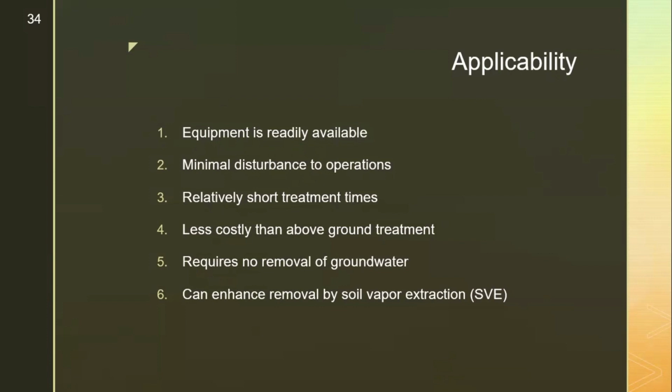Just like most in situ methods, this method is a good choice of remediation if it is taking place in an area where we don't want major disruptions to the ground. Also, air stripping has relatively short treatment times, with the average treatment taking less than 1 to 3 years if performed under optimal conditions. Additionally, this form of air stripping is less costly than operations that require removal of groundwater for treatment. This is more generally an advantage to most, though not all, in situ methods, and will be discussed further in the cost analysis later in this presentation.